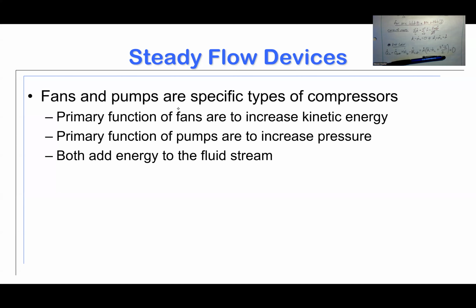Fans and pumps are very specific types of compressors. Again, they are devices that add energy to the fluid stream as it moves through. A fan is often a device that increases the kinetic energy of a gas or a vapor as it moves through, mostly gases. A pump, on the other hand, is often applied to liquids, because liquids don't compress. All you're going to do is increase the pressure from the inlet to the outlet. That's the primary goal of a pump. But in both cases, you're going to add energy to the fluid stream.